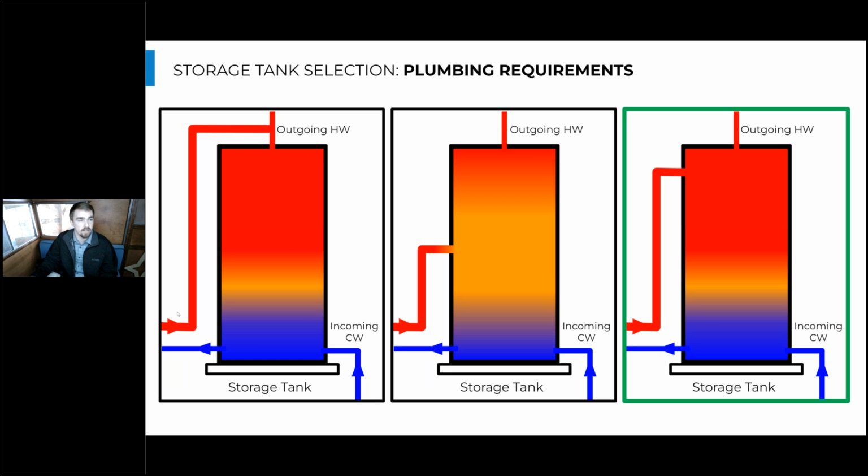So on the left here, you would think to provide the greatest storage capacity, this is the heat pump supply and return. We'll bring the heat pump supply water, hot water, and dump it straight into that pipe that goes into the top of the tank. The heat pump on average supplies 140-degree water. So in theory, that would give us the most capacity out of this tank, while the cold water is pulled directly from the bottom of the tank to be heated up.